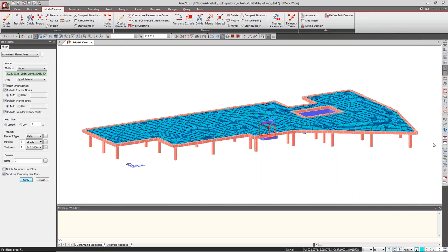Okay, I select this wall and I say planar element. Now because it's a planar element, I just selected these two lines, and now I say it's 0.5 meter. So previously it was 1 meter. Now what I wanted to show you is, I click this element and change the thickness to 250. I say apply.